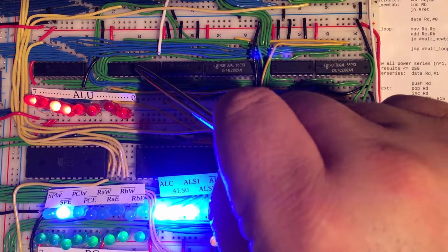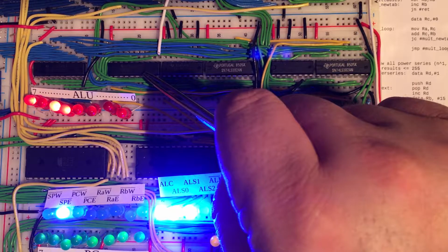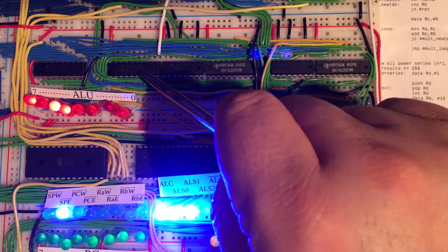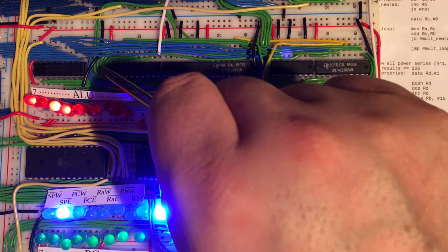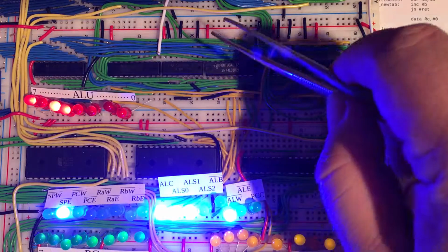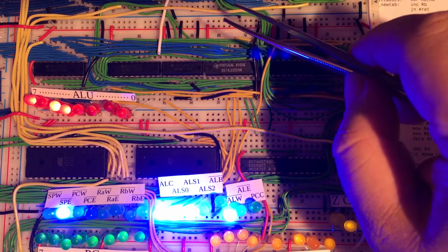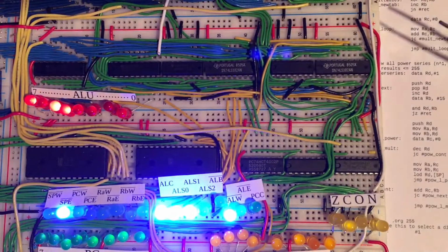And so the inputs to that chip come directly from the ALU, from the calculation unit. And its outputs are going on these green wires here to a buffer chip, and that's the famous 74HCT245, which we're also very familiar with, and that is outputting its contents back onto the bus.